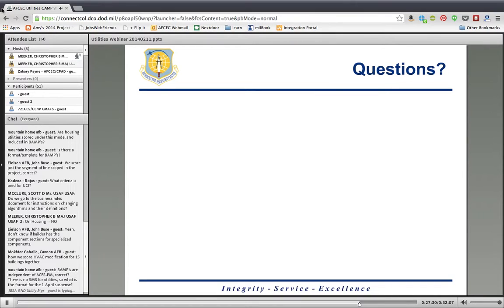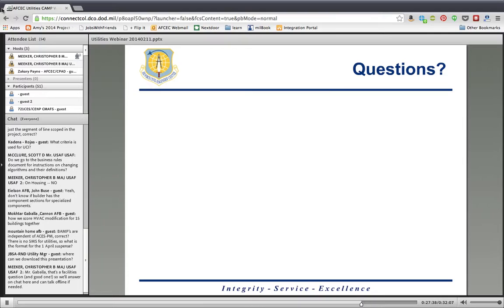And the last one is where we don't have any service life data available either through industry or other sources. So we're going to ask that you do your own direct condition rating assessment and assign it a condition index, and then you go to the worksheets and do a cross-reference for the POF score.